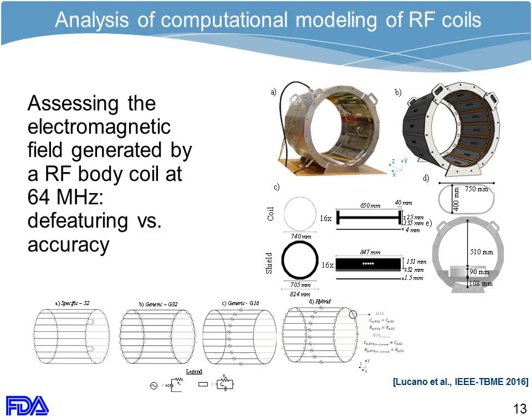But if we are interested in the electric field on a given plane, and this could be the electric field inside a patient near a device, at a specific location of the device, then you can have a given simplification of the coil model, which ultimately allows faster simulations and reduced computational costs, and still accurate results.